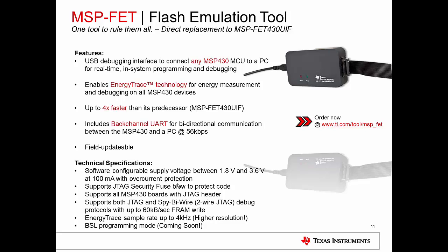Now, on the other hand, the MSP-FET was just recently launched. This is a new tool which will program all MSP430 devices. This is a direct replacement to our previous generation MSP-FET430UIF tool. So it has a USB debug interface that programs any MSP430 that uses 4-wire JTAG or the 2-wire SPI-by-wire mode.